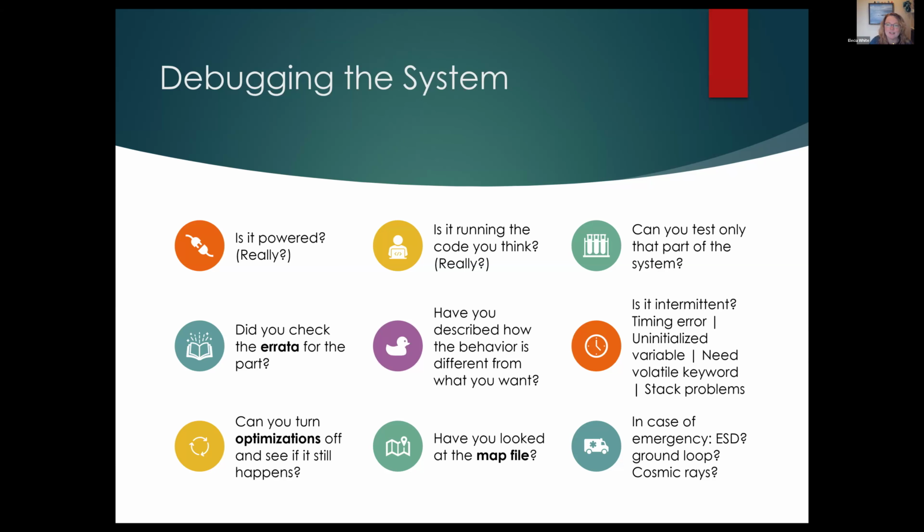Can you put out a list of all the software tasks done sequentially to use a processor for a project? Where does driver development and operating system come in the sequence of processes? Ooh, that is a big question. So first step, requirements gathering. What do you need the processor to do? How fast do you need to ship the device? How expensive can it be? All of these things go into how you choose a processor and how you choose an operating system.